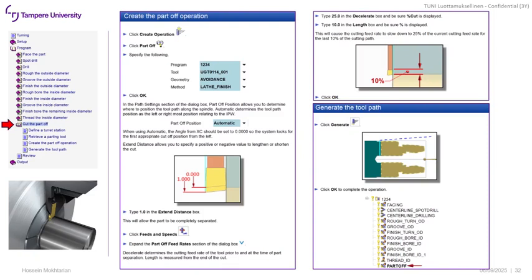If we are going with the same speed, with the same feed, we might actually mistakenly create a deflection on the component rather than really cut it through. So that's why it is better to reduce the acceleration or reduce the speed, like for example here by 25%, as the software is suggesting, but we can of course change it in the last 10 millimeters. So the more we are going to the axis, the more we should reduce the speed or decelerate in a sense.